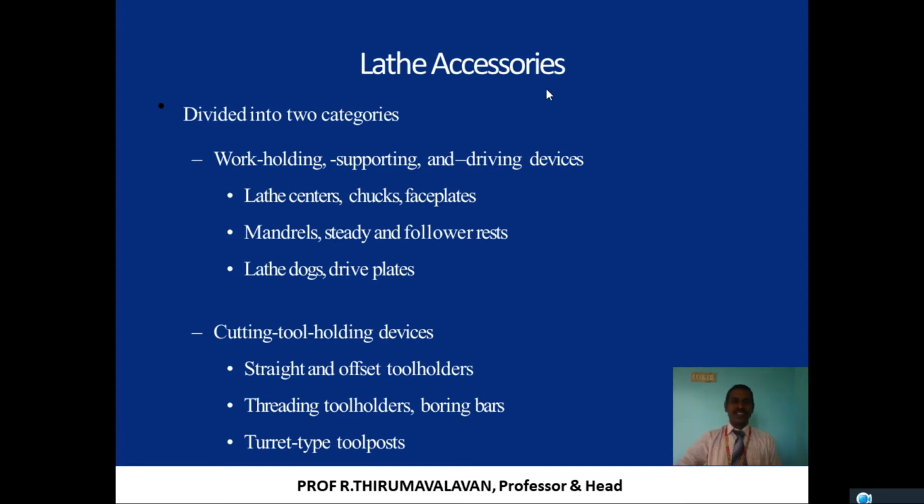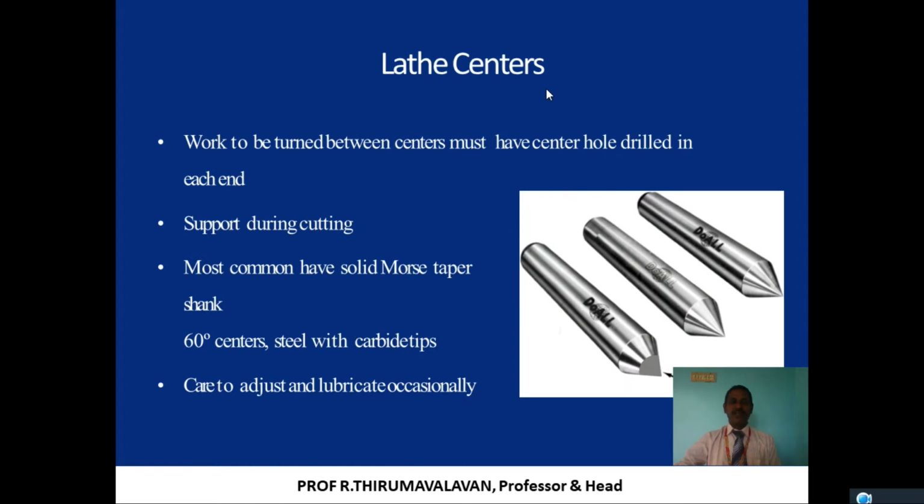What is meant by a lathe center? The lathe center is used to hold the workpiece in between the centers. The dead center is on the tail stock, and the live center is on the head stock. The work turned between the centers must have a central drill: a small hole is drilled on the workpiece to insert the center. This center will hold exactly, supporting during cutting, and give rigid support at both sides.